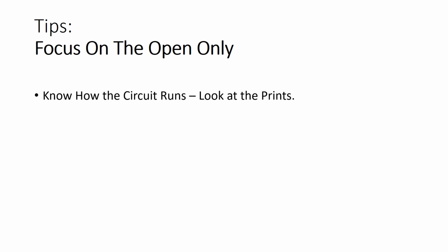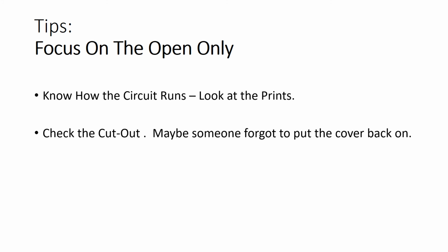Another quick check that might save you a lot of time is to look in the cutout cabinet and make sure the S1 cutout is in place. It could be that the previous crew forgot to put the cutout back in and you're now seeing an open.